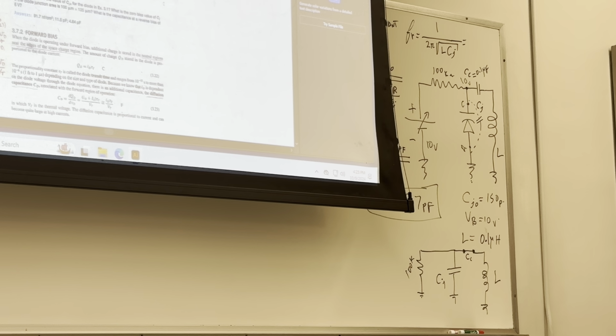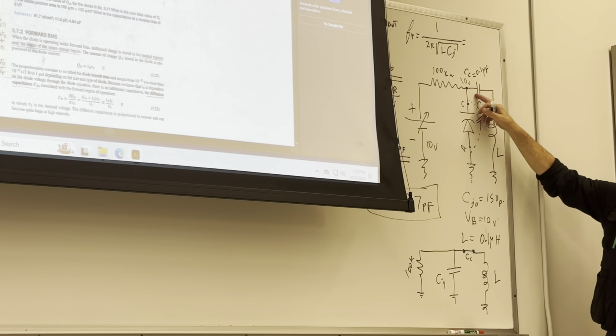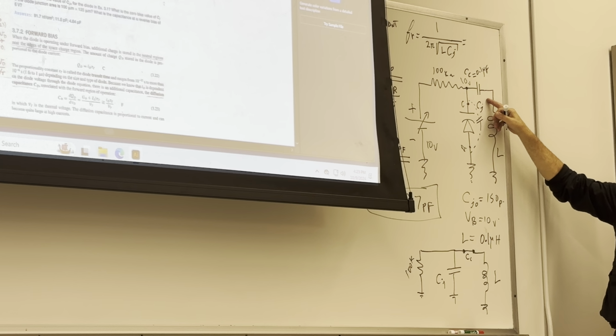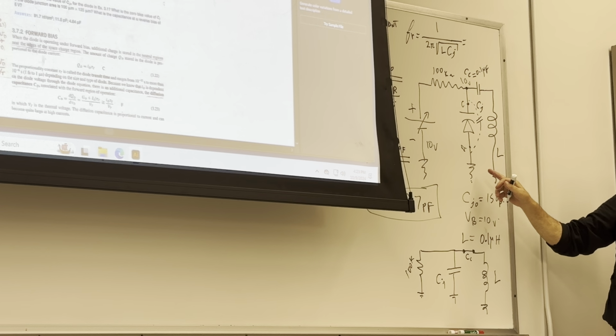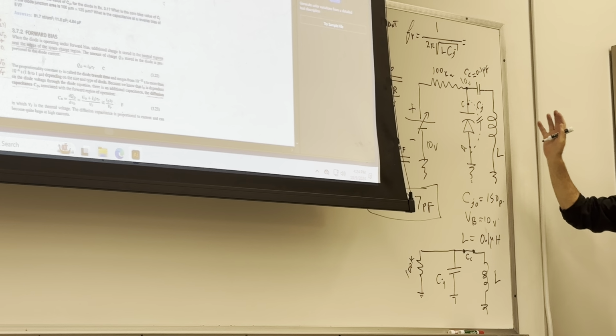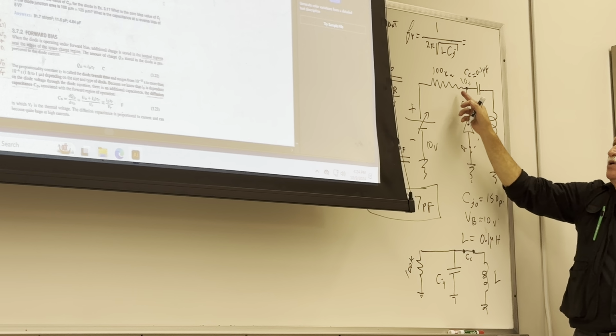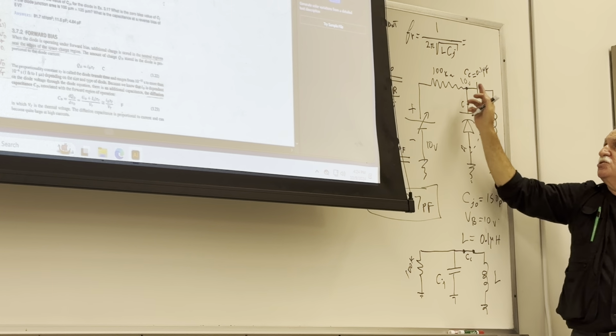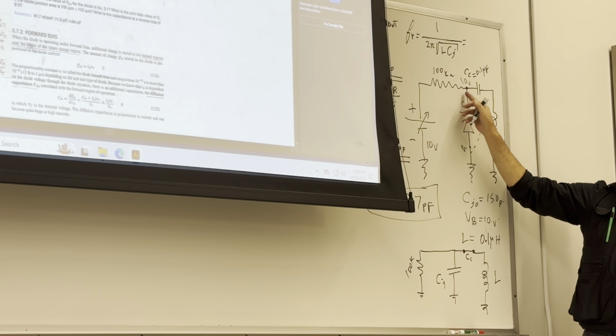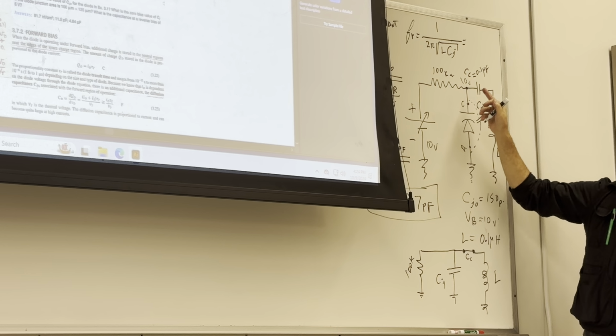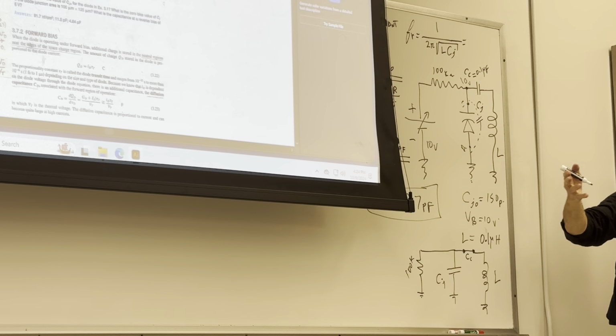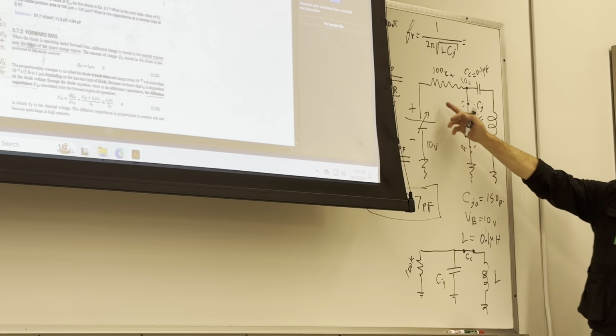Yes? Are we saying that the voltage across the resistor is 10 volts? Or are we saying that there is no voltage across the resistor, it's always 0. There is no current. Because this is 0, okay? No current can be there. No current can be here. This is backward. So all the time, the job of that resistor is to transfer that voltage to diode. In other words, to bias the diode. That's it. What was biasing? Setting a DC voltage somewhere that you want, right? So this is what it is doing.